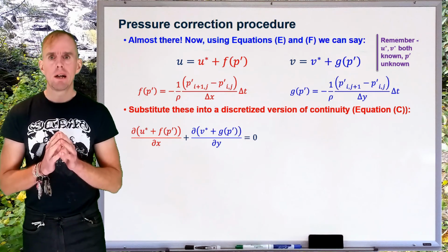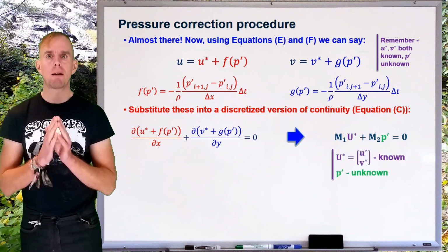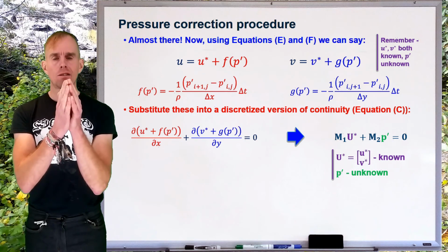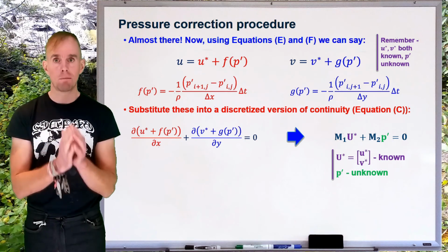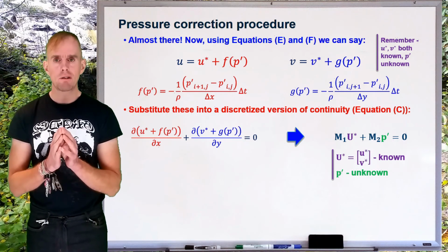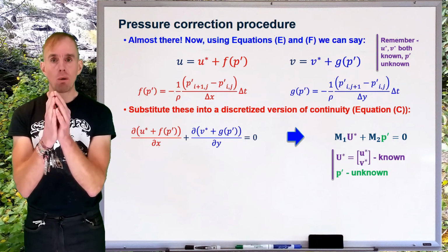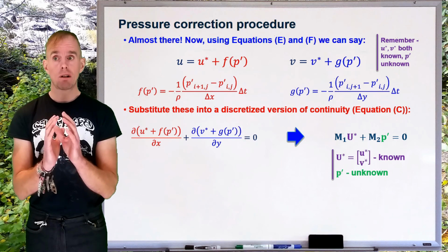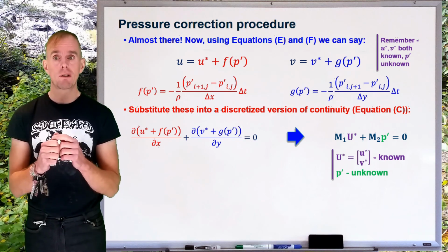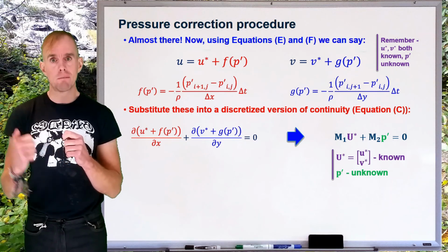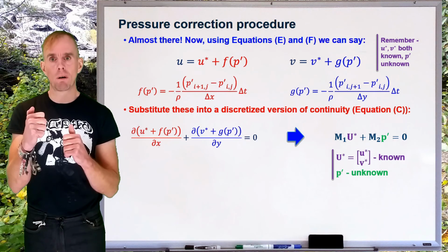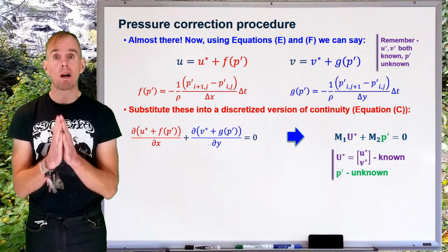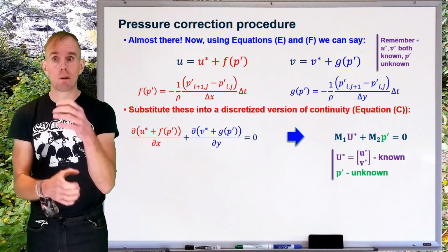Now, what we're going to do is put all the velocity data together in one place. So rather than having a vector of velocity u star and a vector of velocity v star, imagine these as column vectors, if you will, what I'm going to do is put my column vector u star on top of column vector v star and call this big U star. Okay, and so for my spatial derivatives I know that I've got a u star at i plus 1, j, i minus 1, j, and a v star at i, j plus 1, i, j minus 1, and so on and so forth. But all that data of velocity can be held in one vector rather than having to deal with two vectors. We just stack them one on top of each other.